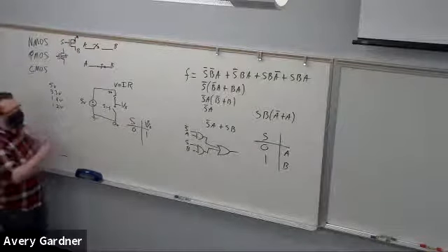Sometimes you will see an inverter, right? So this is our standard symbol of the inverter. If I want to be more explicit on it, I say it's powered from ground to, well, I'll use the symbol VCC. So this symbol is now showing what my supplies are. So I could say that this is 5 volts, for example.